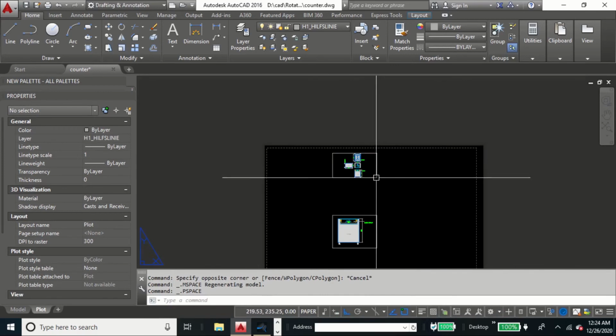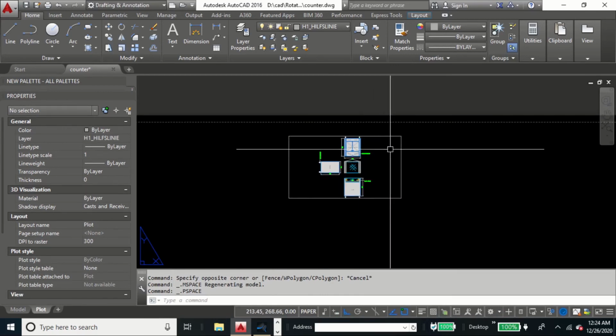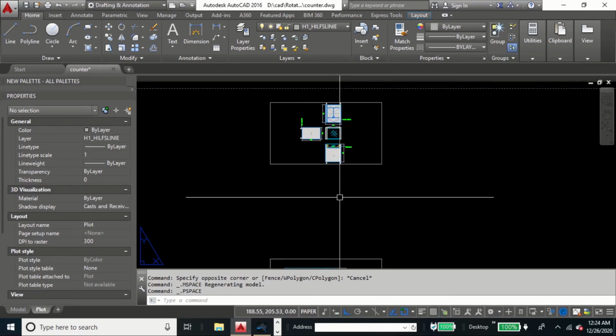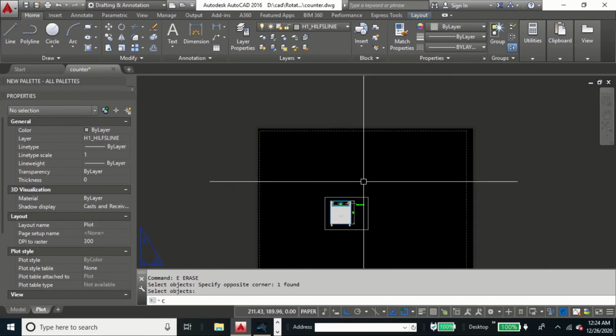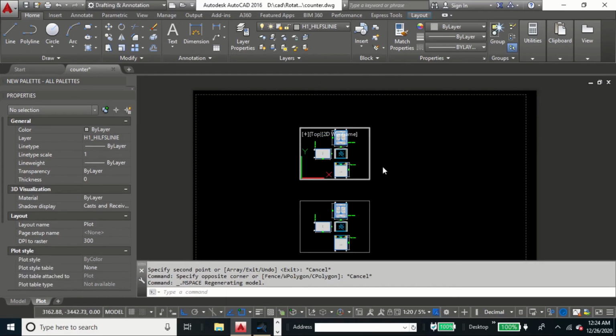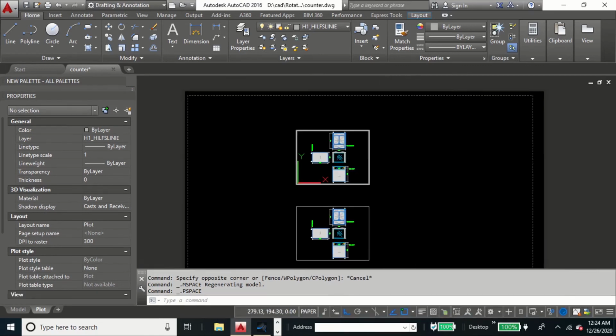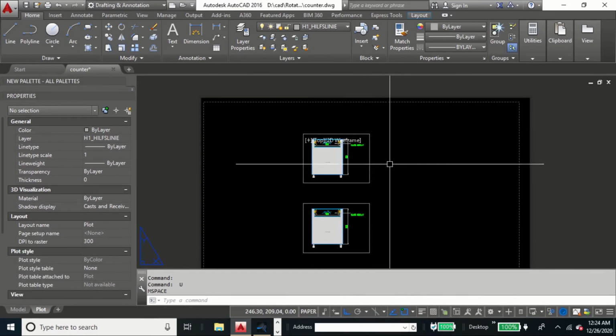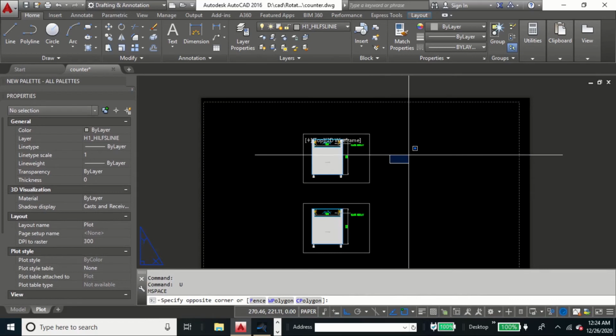See, when I click inside, I'm going to lose that existing zoom level. So here you pick inside and you lose it. This is because of the UCS follow setting which we set before when we wanted to set that UCS icon. So let's change it back again.